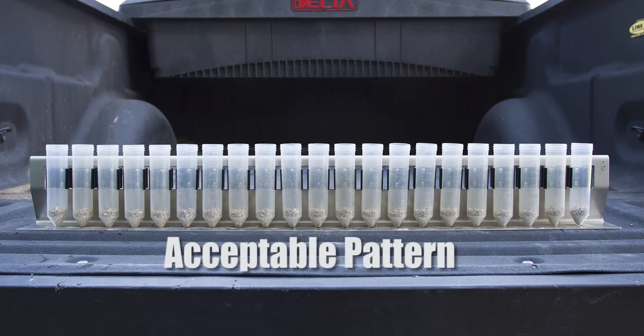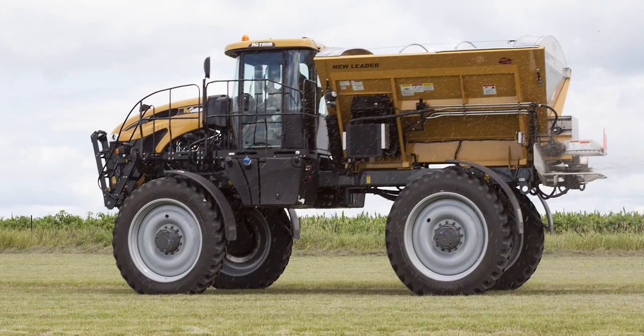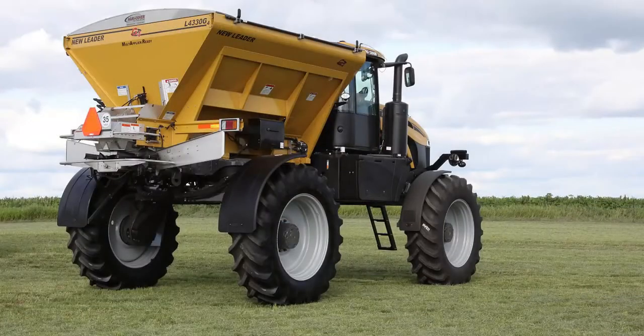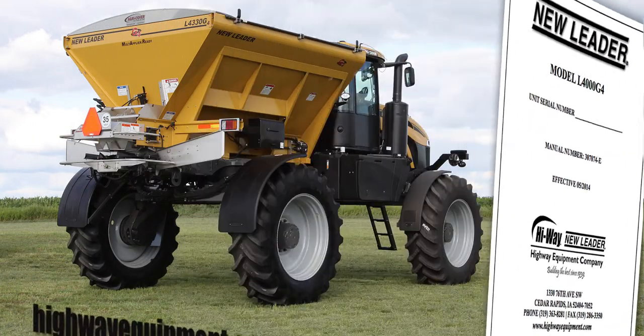When an acceptable pattern is confirmed, document all settings and store in an easily accessible place. Also store this information within the controller itself if the controller software allows. Again, it is recommended that a spread pattern test be performed for all products. It is also recommended to pattern test products at the lowest rate and again at the highest rate that you would apply. For more information and safety instructions, reference the operator and parts manual at highwayequipment.com.